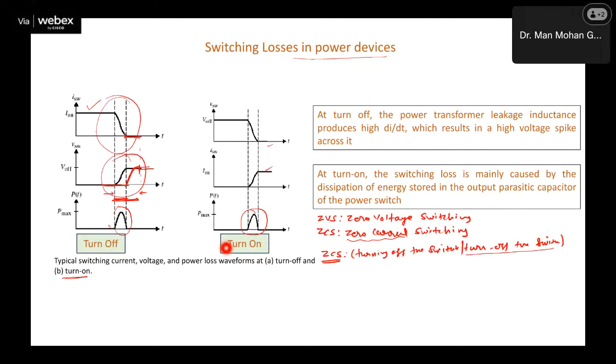If I repeat it multiple times, it means I can increase the frequency. Now the effect of increasing frequency is not affecting our power loss, right? So we can now increase the frequency, and accordingly this period can be controlled by selecting proper resonant converters. This condition is created by using some additional components, so that the voltage will start building up across the switch when the current becomes zero. So that's the fundamental phenomenon of ZCS.